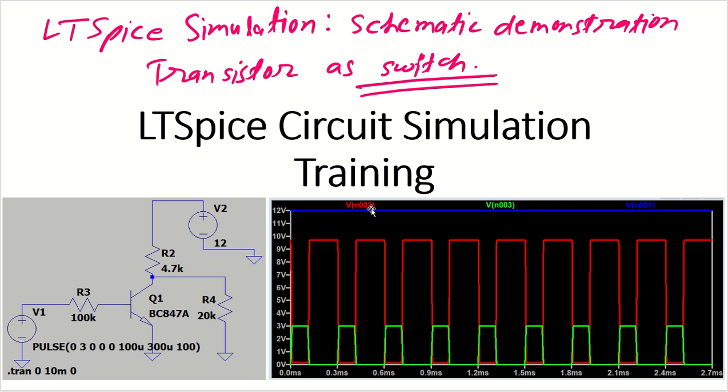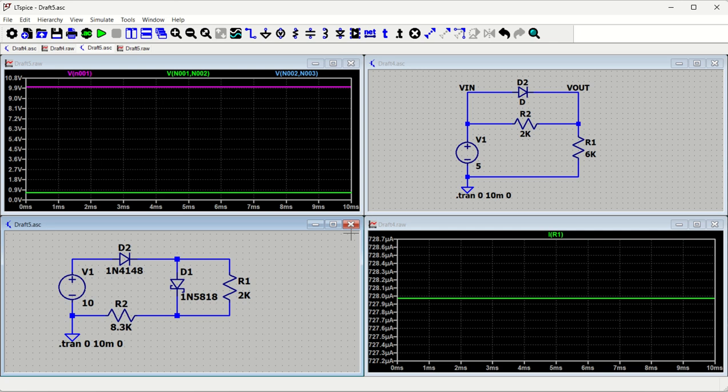Basically you can see, let's open LTSpice and we'll try to understand how this particular circuit works. The basic thing I'll just tell you quickly. Whenever my bias voltage is high, this starts working, and this is my V out. So V out will go low, okay. And whenever the transistor is off, my V out will be high, that is whatever the voltage V2 is, that is 12 volt, which will be there. Okay, so good. Let's open LTSpice and just try to analyze this.